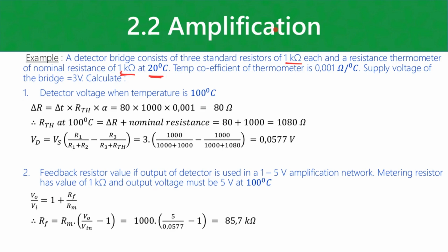Sometimes some of the other resistors will be adjustable, just so that you can get a balanced bridge under your normal conditions of 20 degrees C. Then you would place your thermistor wherever you want to measure the temperature, and have your leads come out of whatever you're measuring in, and then connect to a circuit.